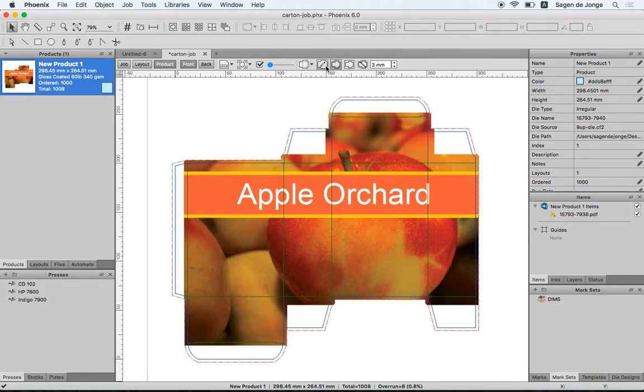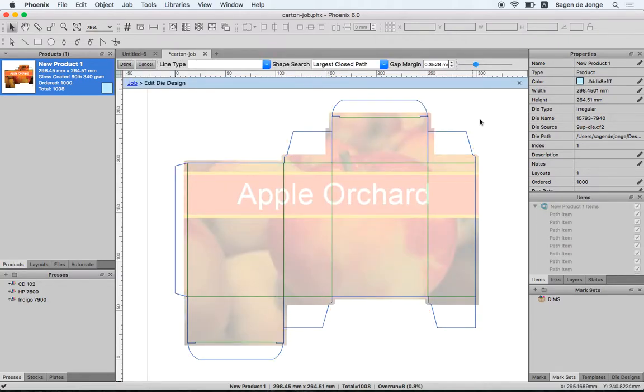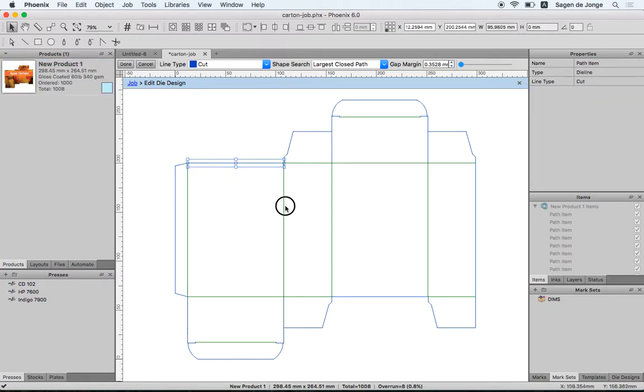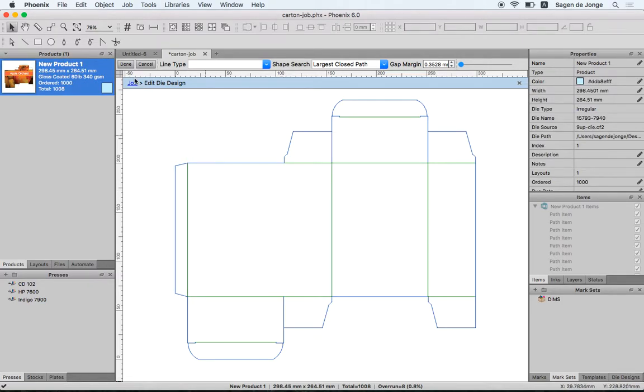But so now I can go and edit this die, and you can see here now actually I get into my view mode where I can start actually controlling these lines. So you can select each different line type. I could, for example, delete lines and then go draw lines back in. Of course, you've got your line tools, your rect tool, your ellipse tool, but then you've got the much more advanced tools where I can start actually go and draw Bezier paths here. And this is going to be your typical type of Bezier tools. You can do straight segments or actually curves like this as well.